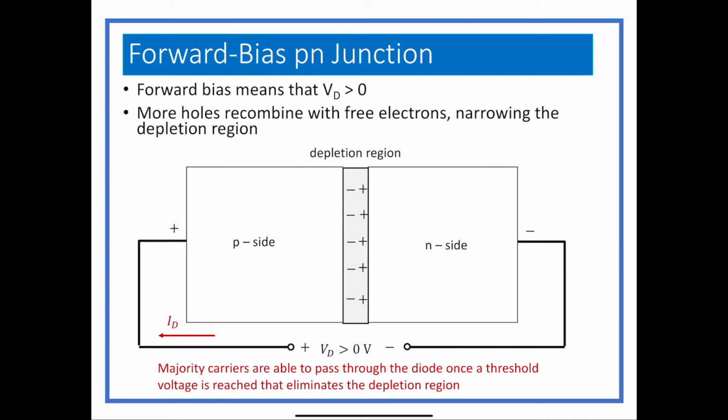And there's actually a voltage across that depletion region, which is kind of like a barrier or a threshold voltage. Once that voltage is crossed, current just flows, and it flows at a rate determined by the rest of the circuit, which is why you don't ever connect a diode to a power supply without a resistor, because that will pull whatever current you can get out of your power supply and will blow up the diode and/or the power supply, depending.